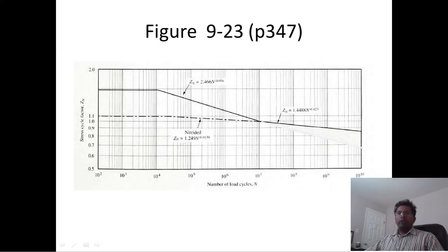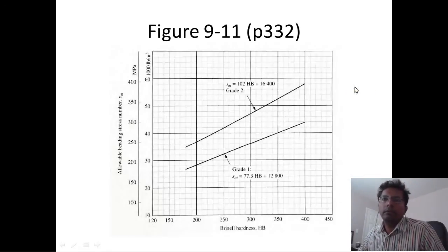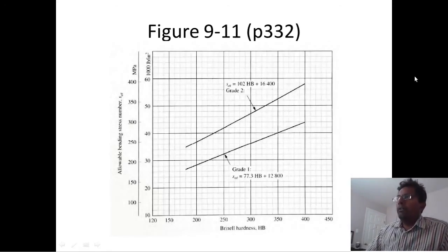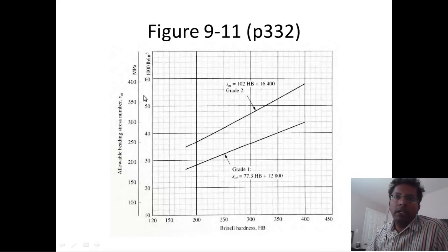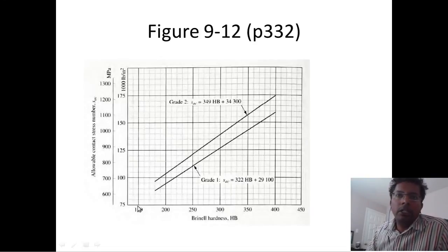So let's pull that figure here. Figure 9-11, that's here. If you recall, we are looking at St prime of 17.59. This is kilo, so this is 20, and you notice that it's not even on the scale, so you're not really concerned about this hardness. The contact stress, which is in the next figure, is 136.6. So let's look at this. It's 100, 125. Between here is going to be 137.5. So that's thereabouts.